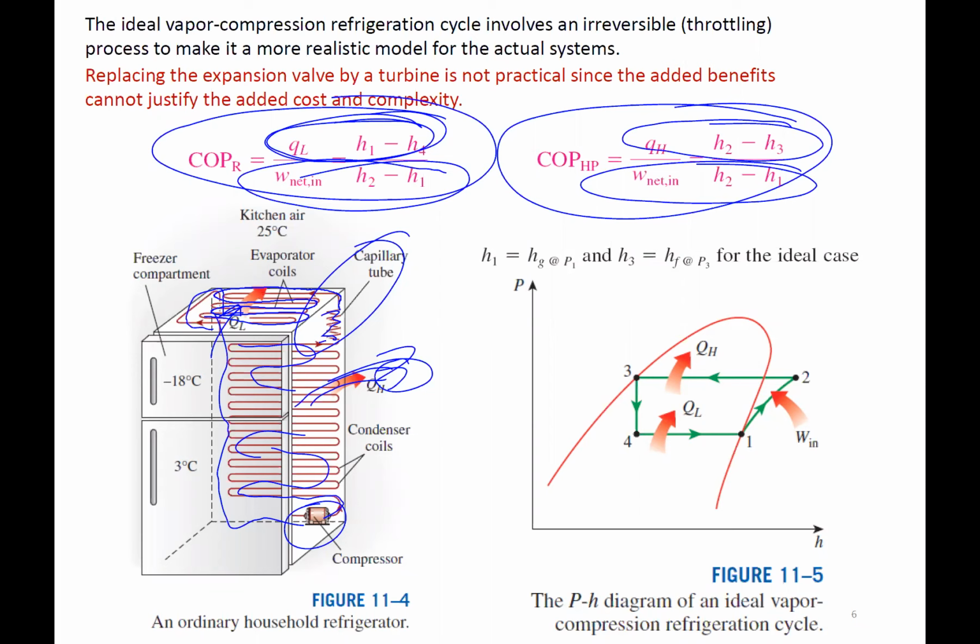In the HVAC industry, they use the P-h diagram. So that's where you see the idea of work here on the x-axis, because you know the work and heat. So we have our energy delta H's here, and then we have our change in pressure here, right? So it gives us the lowdown of what's going on. With 1 to 2, we're putting in work. 2 to 3, we're rejecting heat. 3 to 4 is our isenthalpic valve, or constant enthalpy, and then 4 to 1, again, that's the heat that we're adding.